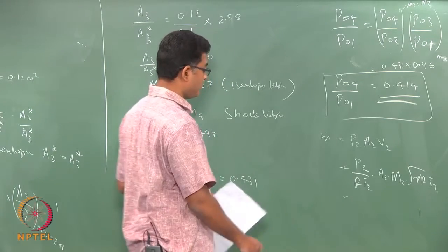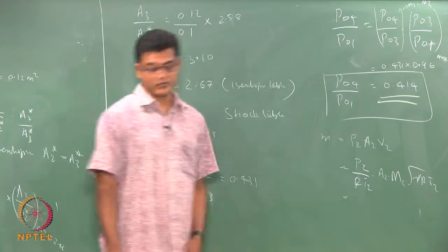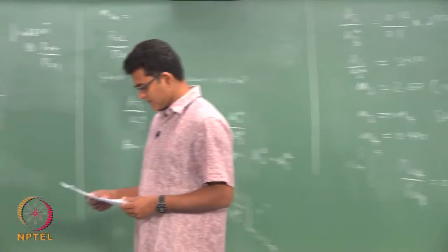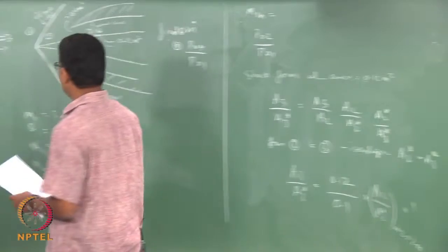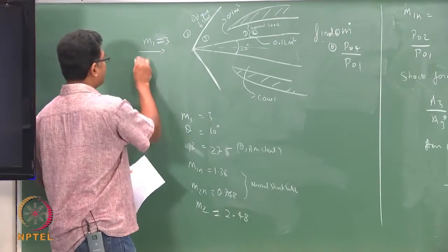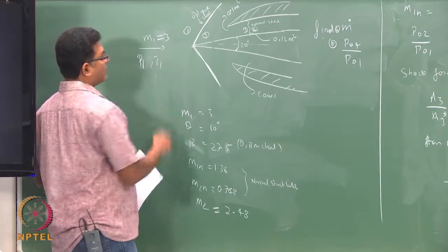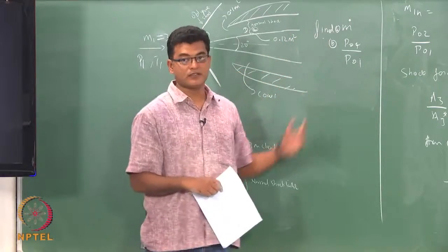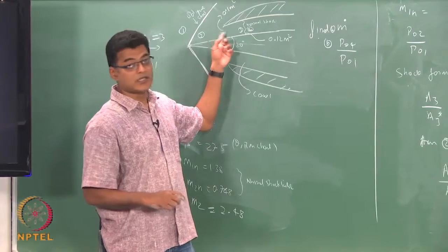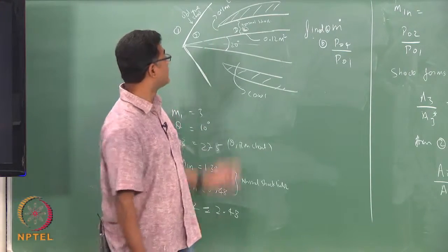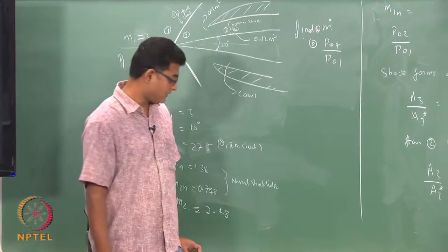If you know your T2 you can get your m dot. Okay. So, along with the inlet Mach number, if I give my P1 and T1, I can compute the final pressure and temperature and also the m dot that is going through the cowl.